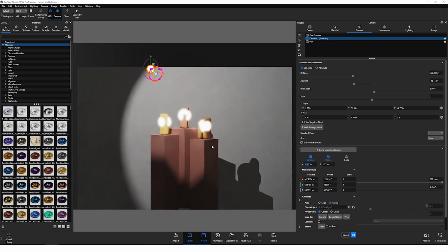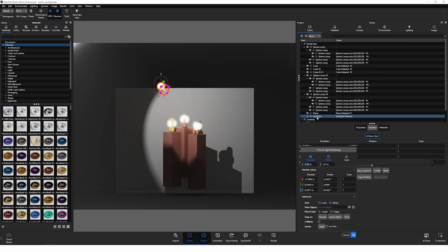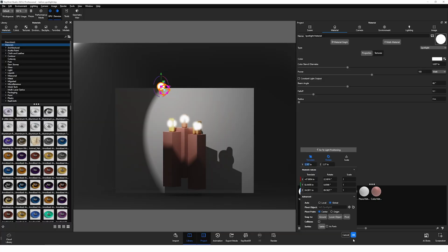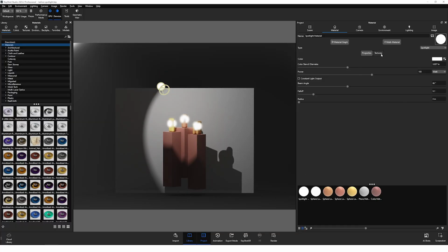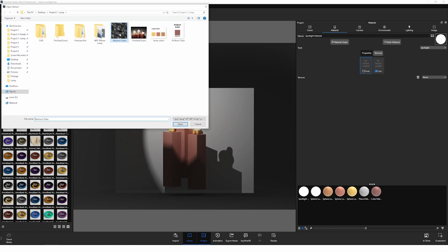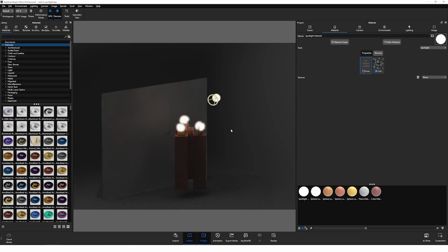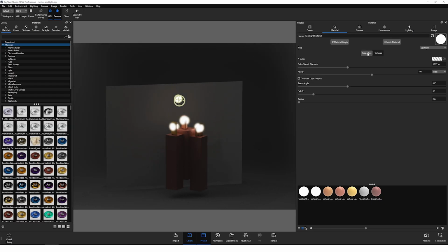The first step in this process is to double-click into your spotlight in order to access its settings. Once inside the spotlight settings, click into the Textures tab and click on the box named Color. In real life, metal discs are needed to block the spotlight's beam, but in KeyShot Studio, all you need is an image texture. After selecting an image on our PC, all of the light from our spotlight appears to be blocked. This is simply a scaling issue.